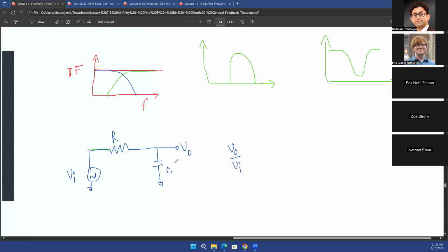Now, when you learned about filters a little bit, you know that we generally consider the resistance as a quantity that has an equal value of impedance over all frequencies. Like resistance is just resistance. On the other hand, capacitance or inductance can have impedances which are frequency dependent. The impedance is just frequency dependent resistance. And for a resistor, the value of the resistance does not change with frequency. Right? It's flat.